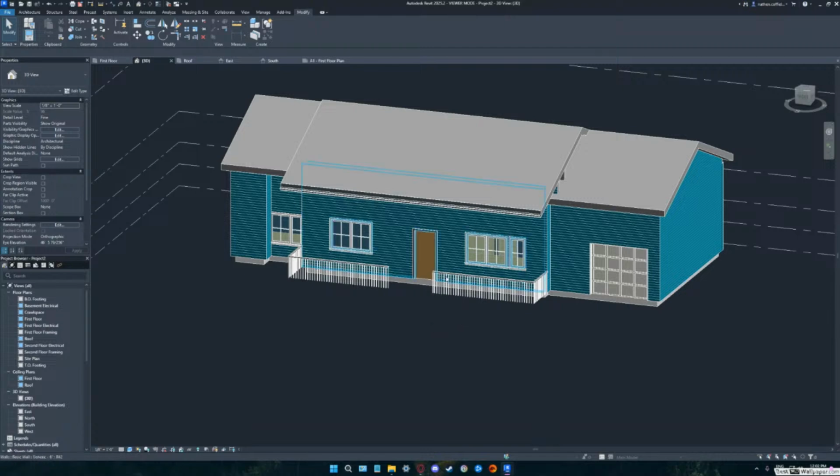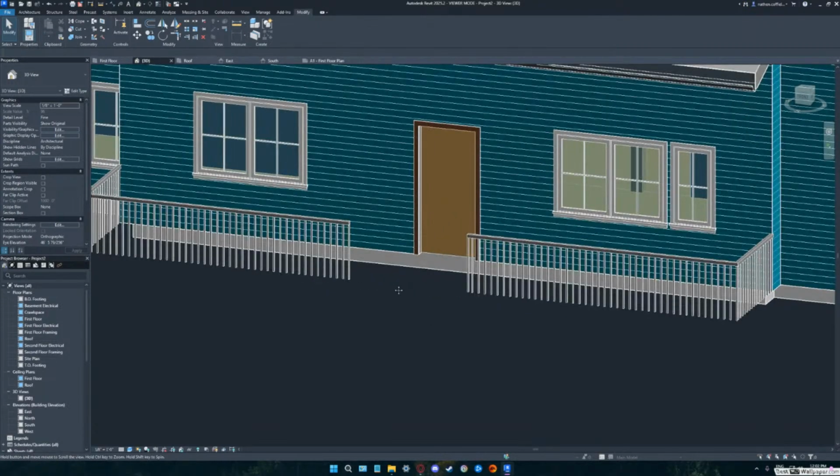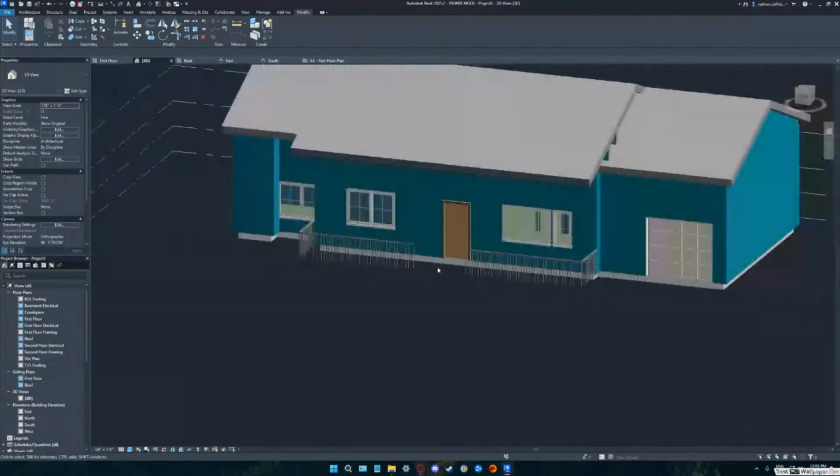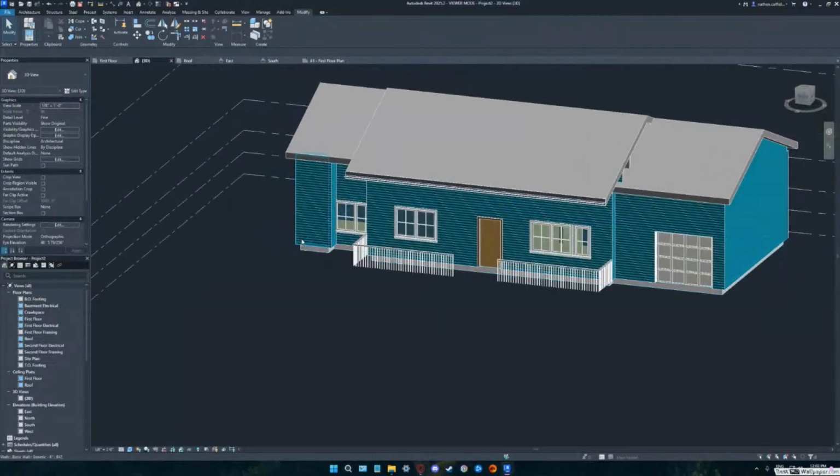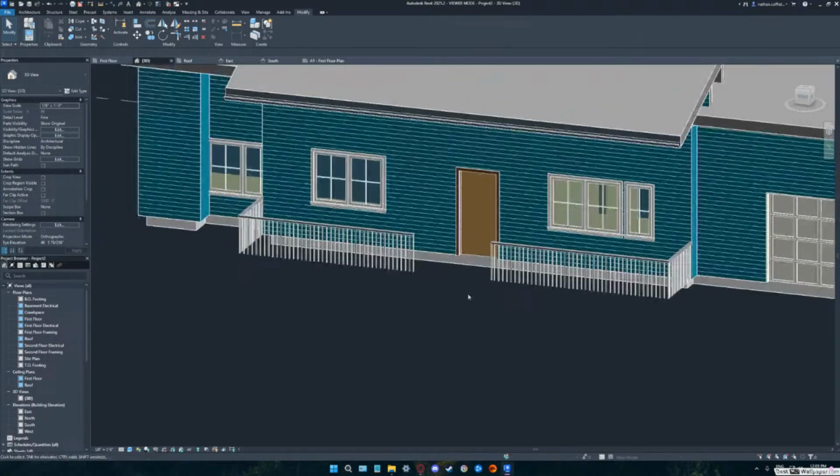Okay. This patio and this decking, would this be on the same level as my flooring? Not typically. Typically, that would want to step down at least 2 or 3 inches. The reason being, you wouldn't want rain to come up on that porch and go right underneath your door. Okay. But I don't think I would make another level for it. I would just put